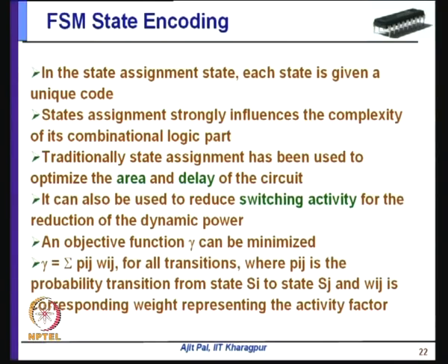Traditionally that is what is being done, but the state assignment strongly influences the complexity of the combinational part of the circuit, which affects the area and delay. However, now the state encoding is being done to reduce the switching activity for the reduction of the dynamic power.